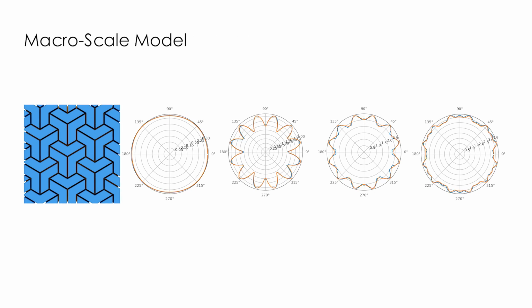We use these data to construct a novel homogenized energy model that combines biquadratic uniaxial fits with polar interpolation based on circular harmonics. We show that this homogenized energy can be combined with standard discrete shell models to enable efficient simulation of large-scale patterns.